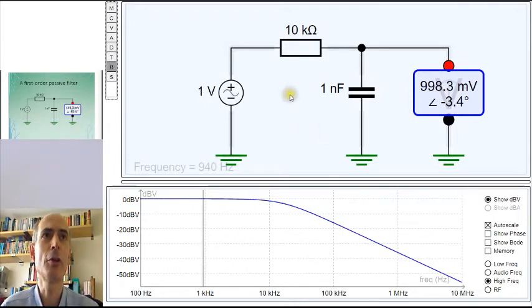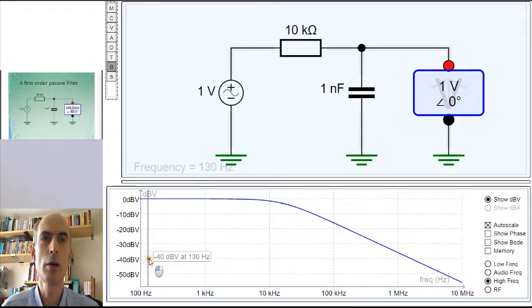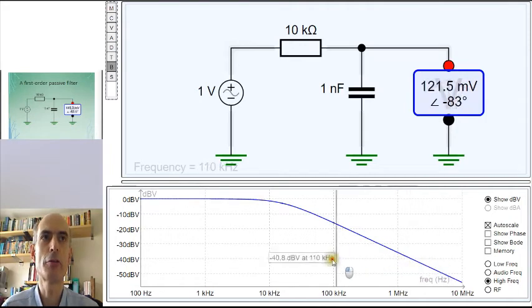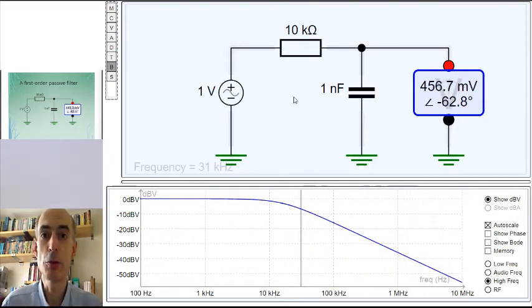The circuit in this simulation is a simple low-pass filter. It has a large output, approximately 1 or 0 dB at low frequencies, and attenuates the signal much more at higher frequencies. If we analyse the frequency response of this, we would find it had one pole at -1/RC radians per second, and it has no active components, in the sense that there are no components in that circuit which require a power supply. This makes it a passive filter.